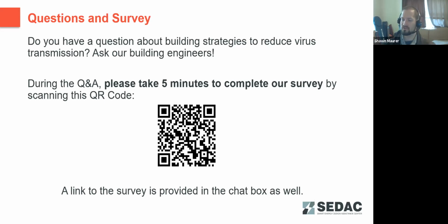And since they are circulating, usually with occupants in the space, you get thermal patterns that rise out of the airstream. That's going to bring contaminated air from occupants up with those thermal plumes to that unit. They do have a very high effectiveness as far as clean air delivery rate. But again, cost is probably the main consideration for those units. You've got to mount them to the ceiling, so you've got to have some additional support to actually support the weight of that unit. And then the cost of the unit itself with those additional technologies is an important factor.